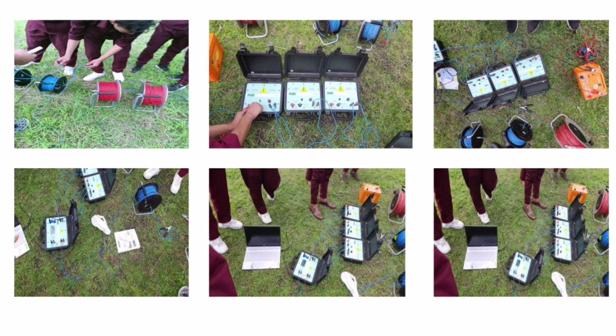The basic principle of ERT is that the current is induced in the ground using two current electrodes. The electrical potential drop is then read using two other electrodes. A constant current is injected into the ground from the ground resistance tester through the two outer electrodes. The voltage drop resulting from the current flow through the ground is then measured across the inner two electrodes. Most instruments are designed to provide a direct reading in ohms.